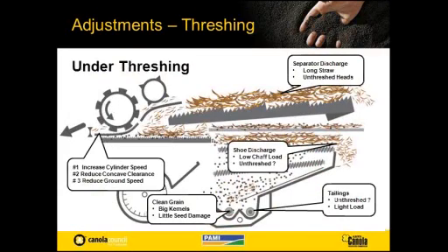Now, if you're under threshing, what you're going to find is that you've got a lot of long straw going over the separator, and there's going to be heads attached.